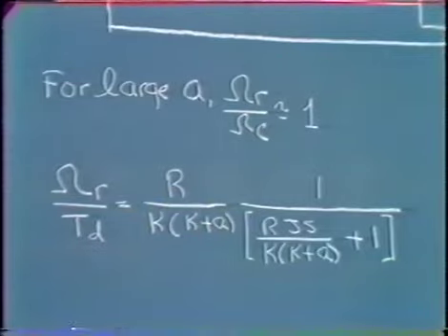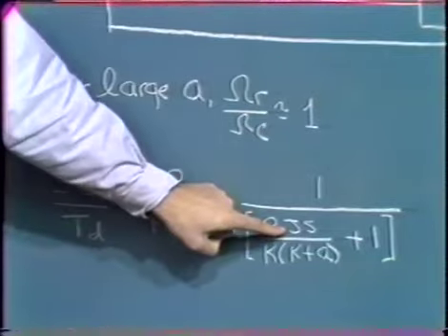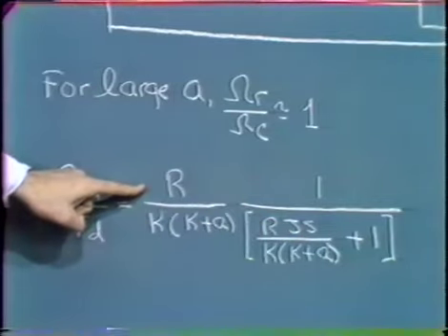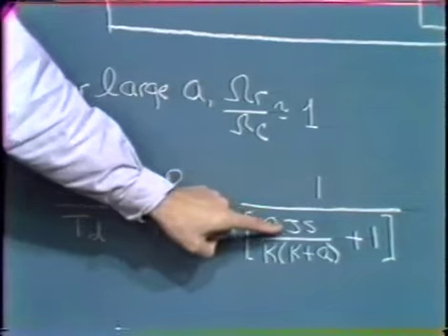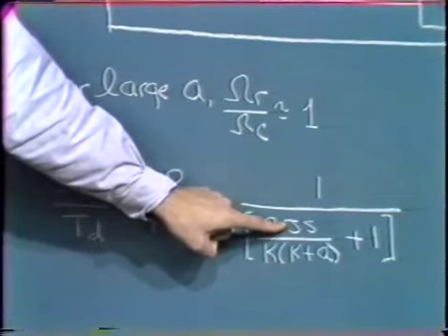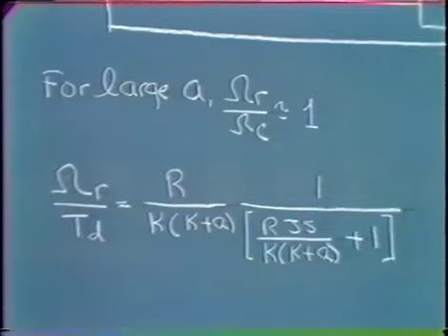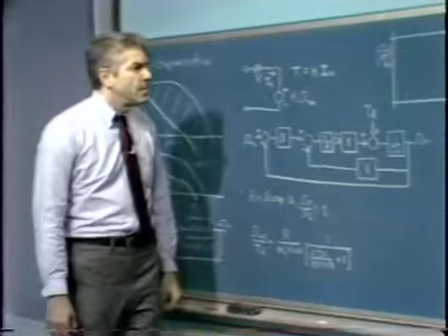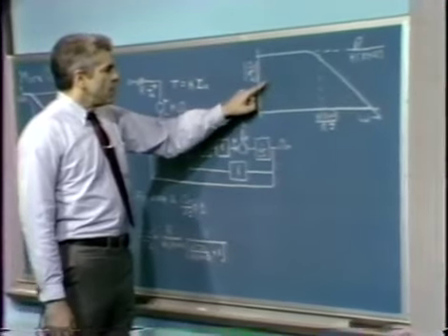The important point to note is that if we increase the inertia in this expression, it doesn't change the low frequency rejection at all, but what it does is lower the frequency at which the pole comes in. And we can look at the effect on this transfer function of changing inertia in Bode plot form. And I show that over here.